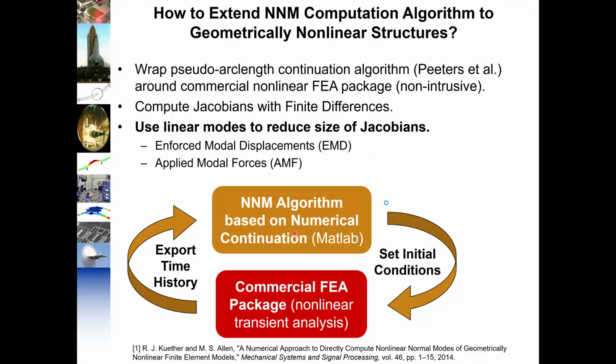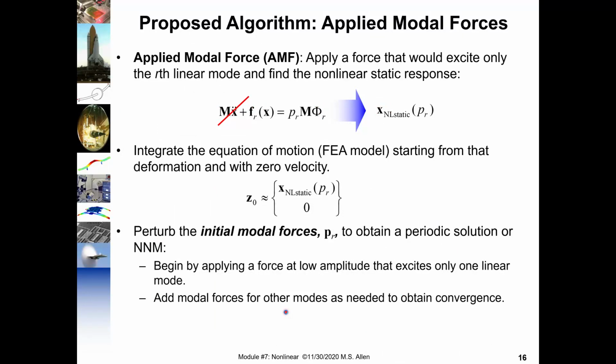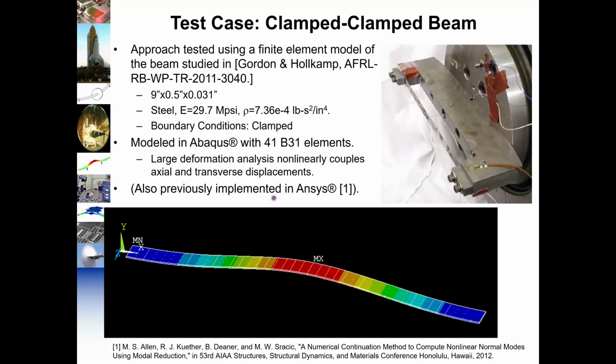So again, I won't go into the details, but basically we took an algorithm similar to what was on the previous slide, and we wrapped it around a commercial finite element package. And there were some tricks we had to do to deal with the large number of degrees of freedom. I won't go into those here, but it basically involved applying a static force to the structure, finding a static response, and that static force was in the shape of a mode, and then using that as an initial condition when we integrated the system. Anyway, long story short, we were able to develop an algorithm that could do this.